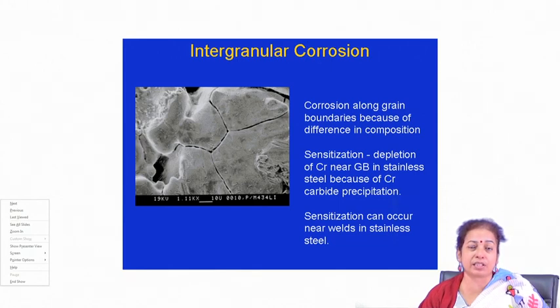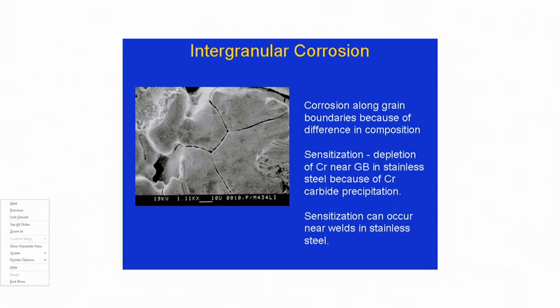But though the initial kinetics is much higher, gradually a very thin and highly adherent protective film forms, and that film is usually much stronger in nanostructured materials than in annealed coarse grained materials. As a result, the corrosion rate of nanostructured materials is usually lower than that of coarse grained microstructured materials.